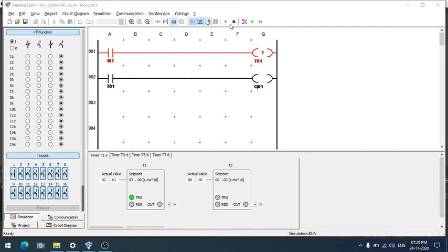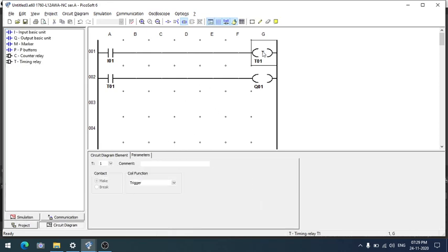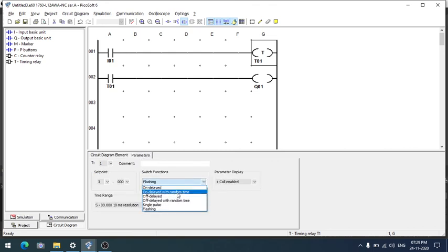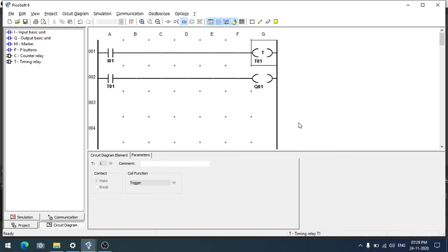Okay, these are all the different timers. Apart from this, we have the on delay and off delay random timers also. With this on delay and off delay random timer, whatever time value we give here, it will always take some random time within the set range and then start to work. This is the off delay and on delay random timer. So that's all about timers.